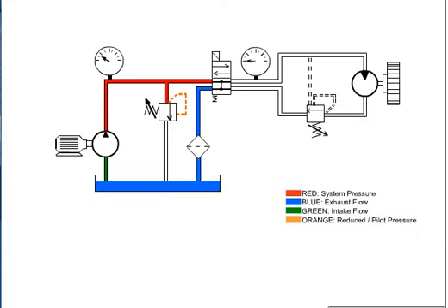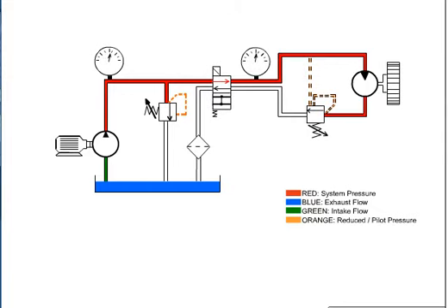A brake valve is a normally closed pressure control valve with both direct and remote pilots connected simultaneously for its operation. This valve is frequently used with hydraulic motors for dynamic braking. Because any downstream resistance will add to the load on the hydraulic motor, we pilot remotely using working pressure to keep the valve open during running. This eliminates back pressure on the motor.